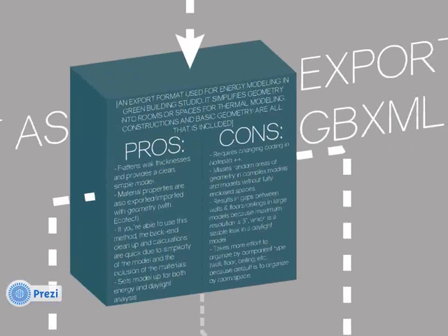So GBXML is probably the opposite, the most different export pathway in terms of its file type and its parameters. What's nice about the GBXML process is it simplifies the model, and now there's automatic simplification within Revit. Beforehand, to get to GBXML in Revit, you had to go room by room, enclose the volume, 100 times if there were 100 rooms. Now there are really great embedded analytical capabilities where we'll interpolate those room volumes automatically, as long as everything's room bounding. They've automated the process on the Autodesk side to get it to the GBXML format, which is really nice.